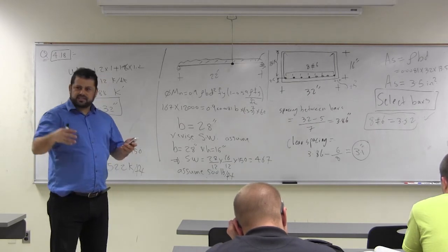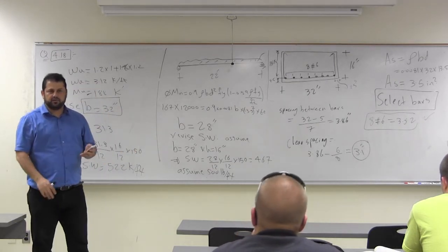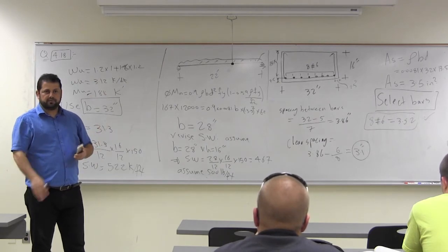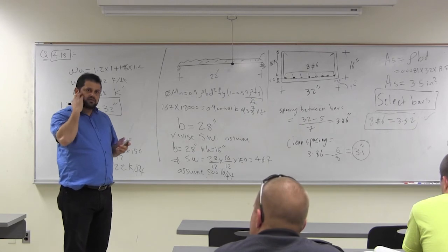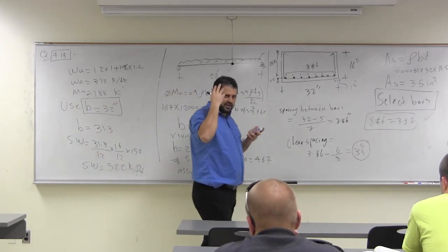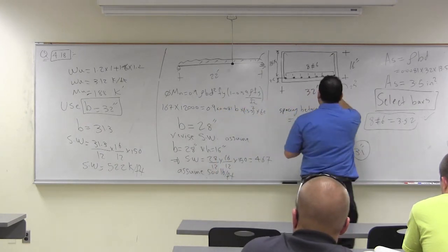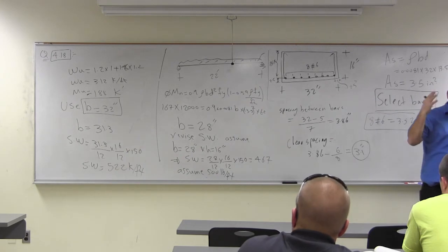Okay? This is given information. You go to any sketch, you will see this in the ACI code. Chapter 1 or 2. The one that we skipped because it's background information. Okay, guys? Just keep in your mind. Just take it like that. At least equal to the cover here. And usually the cover is 2 inch to 2½ inch to the center of the bar.